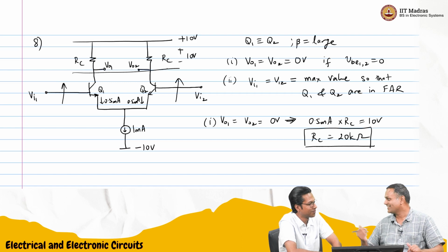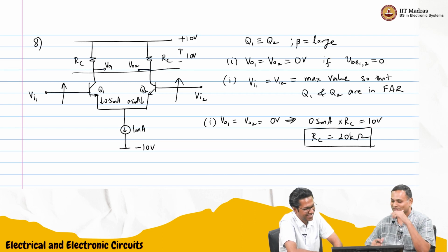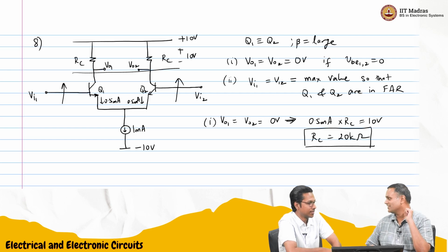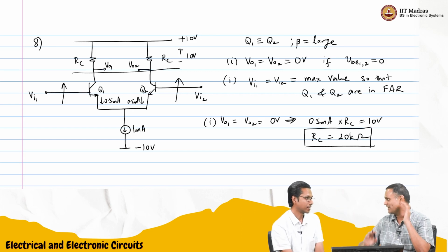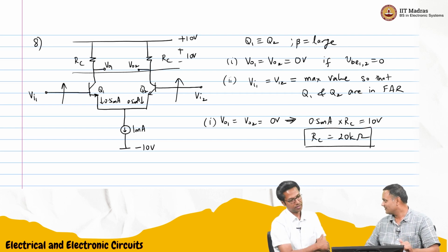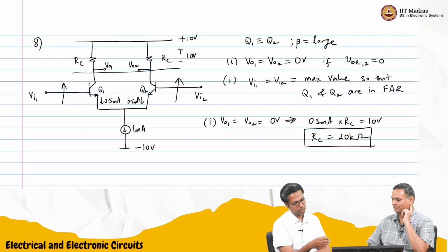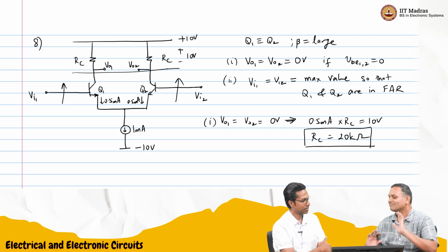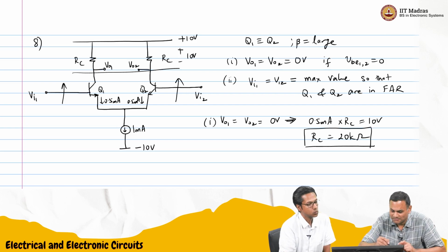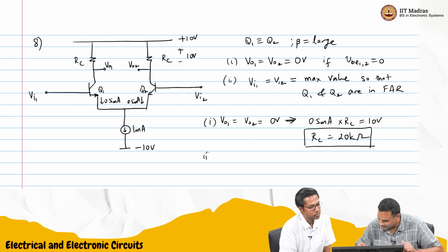I like the question that you have set. The collector voltage is constant, and the base voltage keeps increasing. So the collector base junction will eventually go from reverse bias to zero bias to forward biased. You want to find out the point when exactly it is zero biased, because beyond that, if we give an input voltage, it's no more the amplifier that we are expecting. So how shall we write this condition?